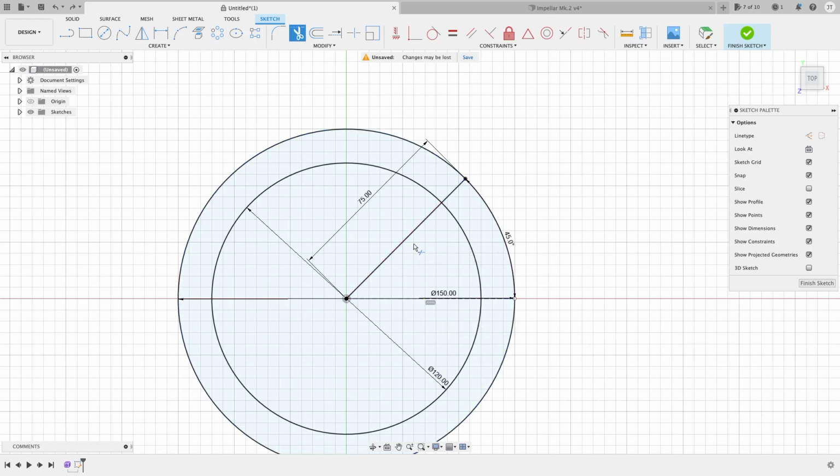So what you do once you have the trim tool active is you can hover over the segment of the line that you want to get rid of, such as this one, or if you want to get rid of this one. Obviously we want to get rid of this one, so as you can see it is highlighted red and we simply click, and as simple as that, we have gotten rid of that line, but we have a reference point of a perfect 45 degree angle from our origin point over to here.